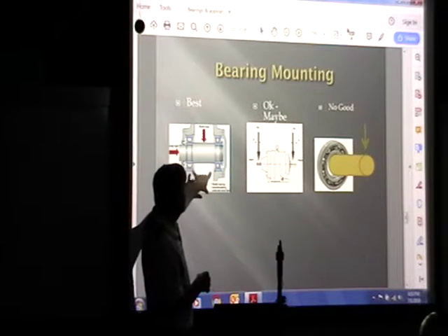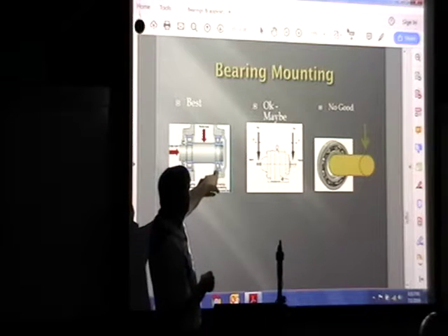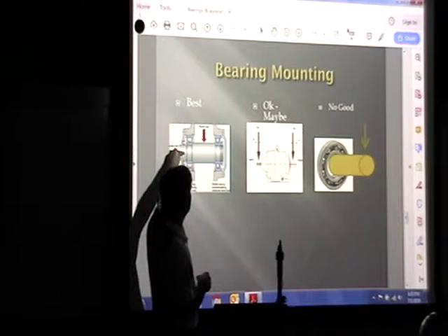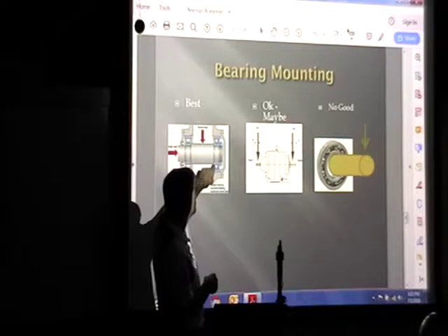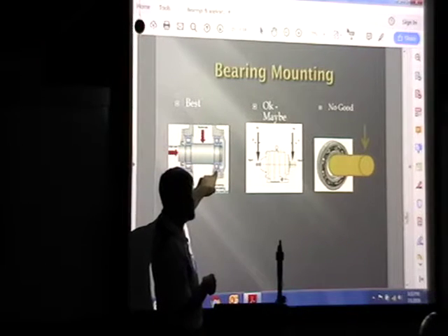In this particular arrangement, they've got a roller element bearing and a ball bearing. The reason for that is they also are predicting an axial load. So an axial load goes through the shaft, enters this bearing through this step in the shaft here, and then through these roller elements out to this axial wall here.